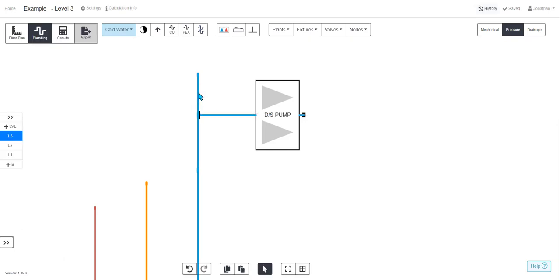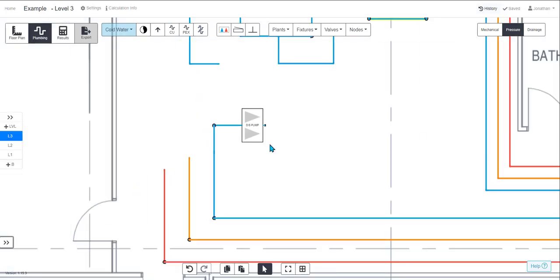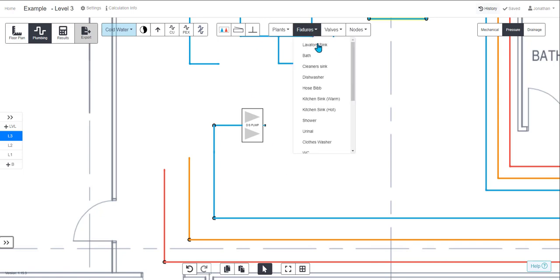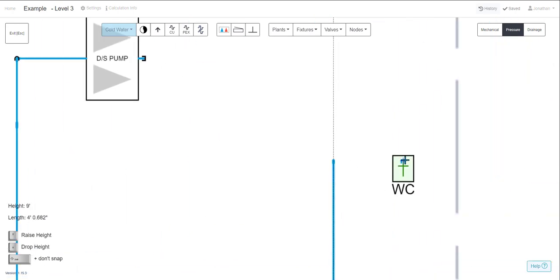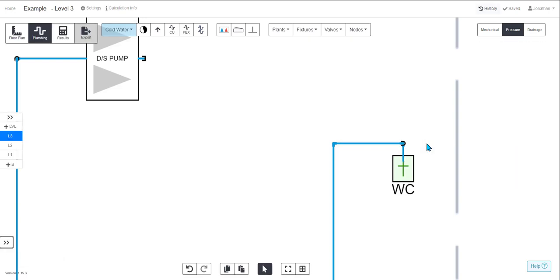Draw in to make the connection, and then you can just click on that and delete that pipe. So same if we had a fixture here. We brought this pipe up and try and hover over it and snap it again, which you can do, but sometimes it's easier and faster to do something like this. So whatever works best for you.